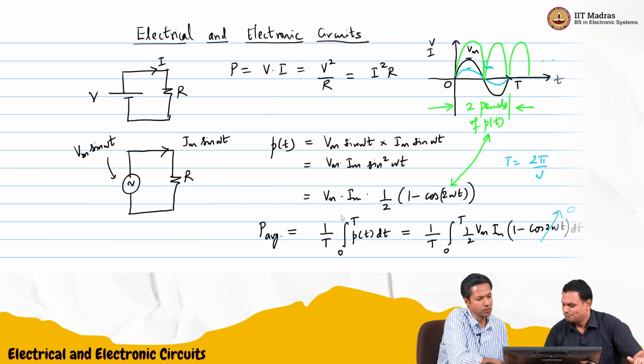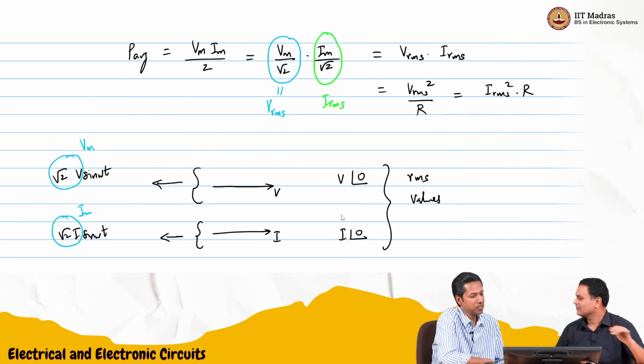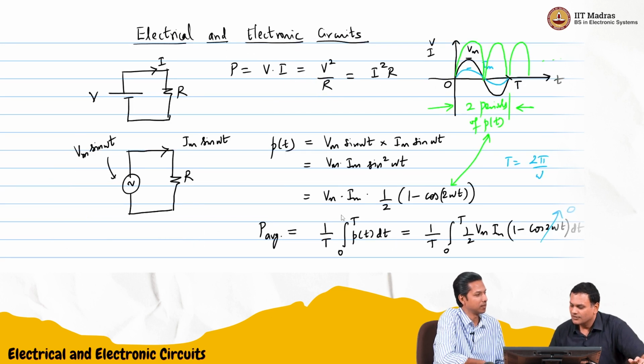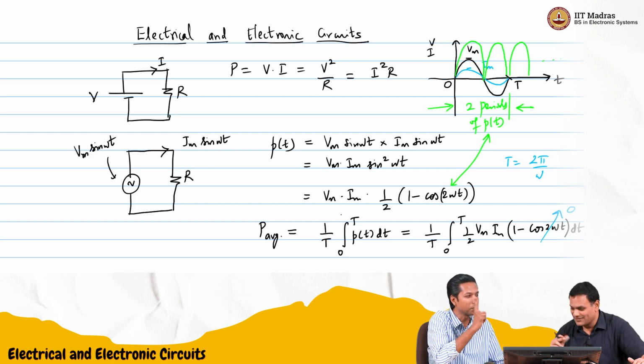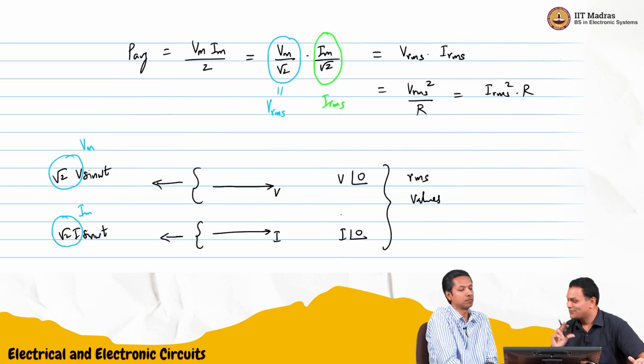Now, resistor, maybe it is easy. If it's an impedance, is it just V into I? Okay, we should calculate it, because we are doing some integration as well. We need to calculate it to be careful so we don't make any mistakes, because the minute you say this is an impedance, the current phasor and voltage phasor will no longer be in phase with each other. So P of t may be different from what we expect. These equations are not going to take care of that. We should be careful. Let us do it.